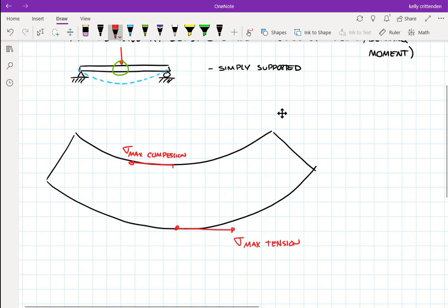And we'll make the line, this is 0 right through the middle here where there's no stress. So this is a negative number, and this is a positive number. And there's some profile that's more or less linear where it goes closer and closer to 0 in the middle somewhere. And then the further away I get from that middle point, it gets more and more on the top side compression and on the bottom side tensile.